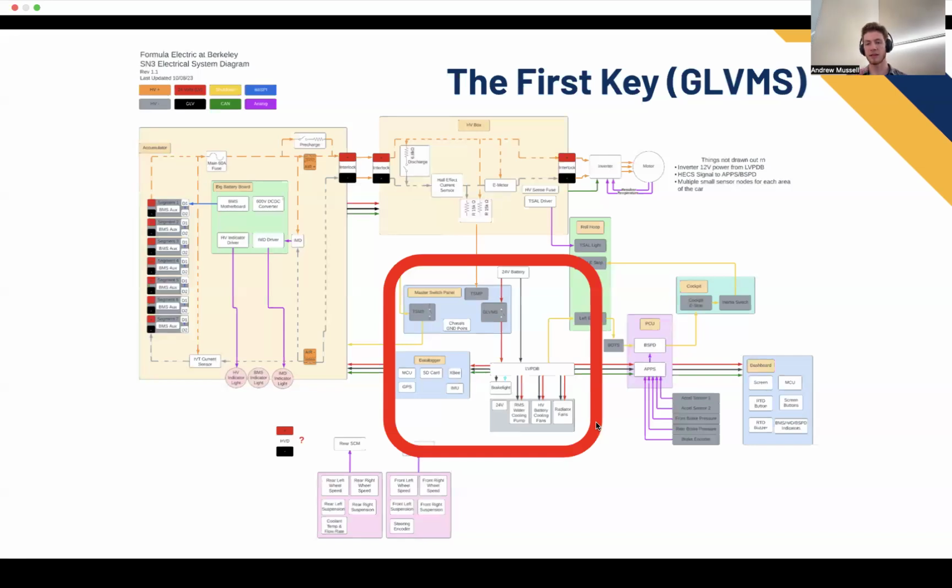And then the final one that I said I would end on is the CAN bus. Throughout our whole car, we have a Cat 5e cable going with RJ45 crimps on the end. That has 4 twisted pairs, and we use 2 of those for 2 separate CAN buses, so that we have a high enough data bandwidth for all of the sensors on the car.